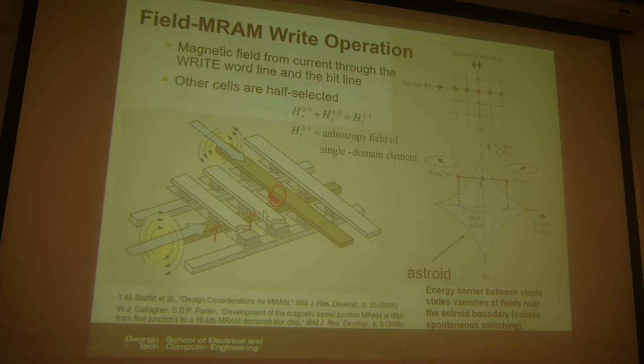So it's like the crossbar array, you have the V and 0, and then those are like half-V biased. Of course, this is not like a V and half-V stuff. But this is the same situation as that crossbar array. You need to design this to make sure only the selected cell at the intersection will have enough magnetic field to change the orientation. The other cells along the write word line or along the bit line will only see half of the field, and you hope that half of the field will not change the state.